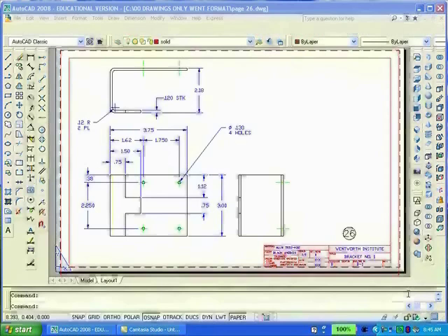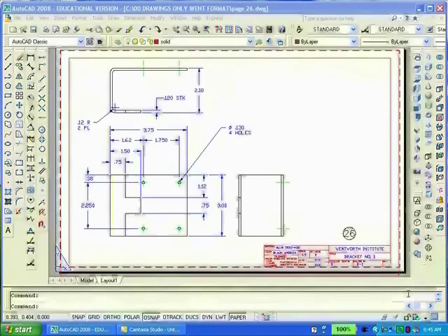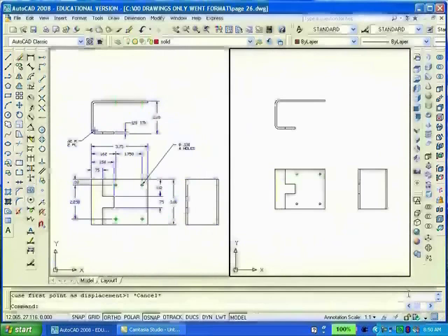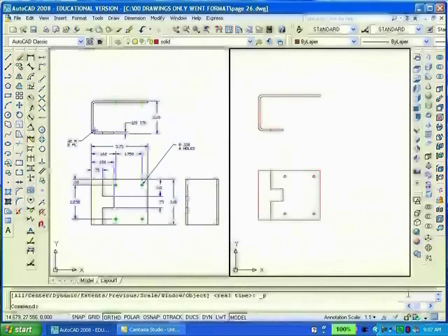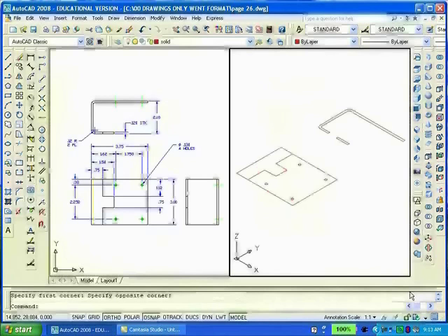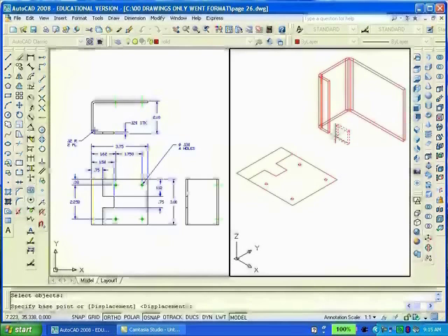This is an abstract of tutorial 26. In this drawing, I used a polyline to trace over the top view, subdividing it into two parts. Then we'll move those profiles to the upper right, and of course make certain that both are closed polylines. I move into the southeast isometric view and extruded the large profile to a height of 3 units and the smaller to a height of 7.75 units. And with the O-snap set to midpoint, move the parts together and union them.